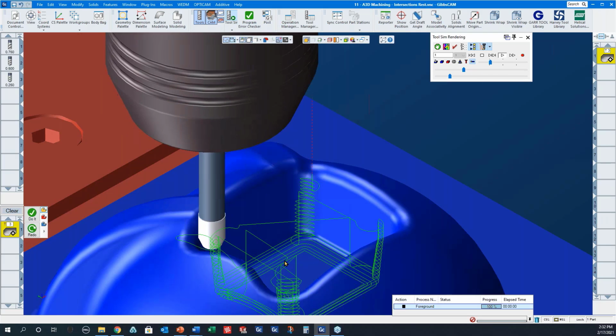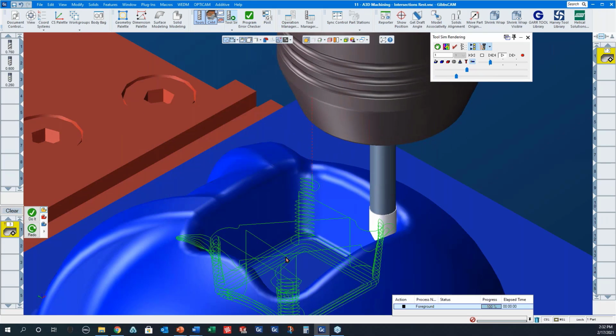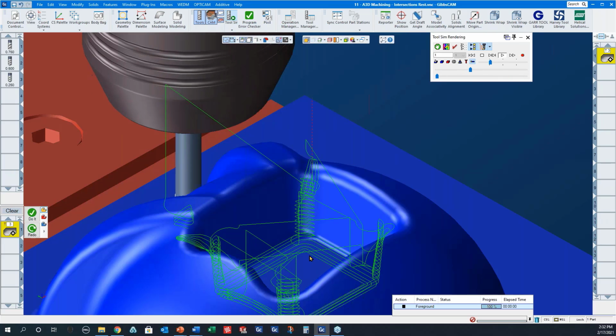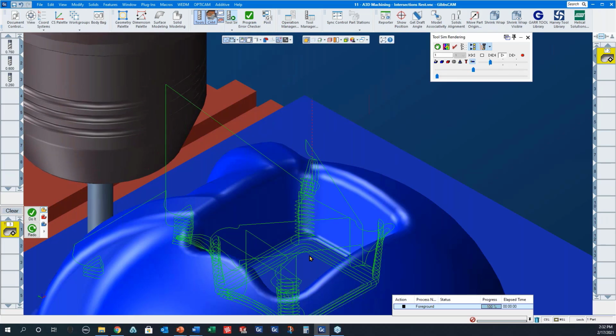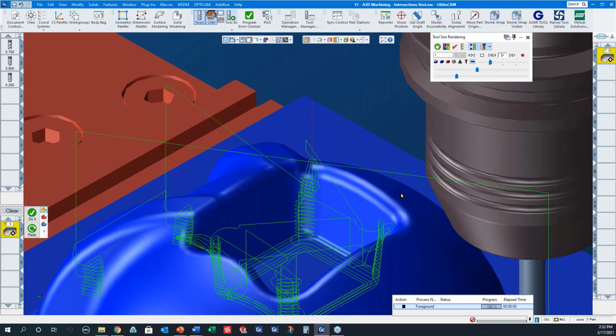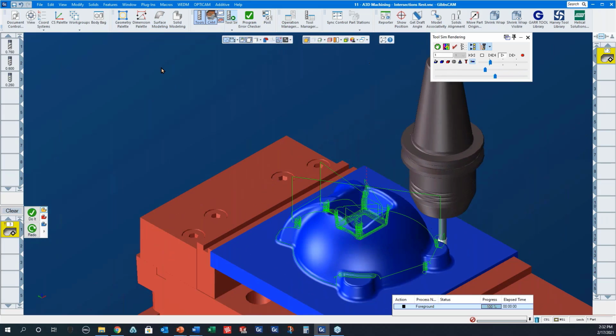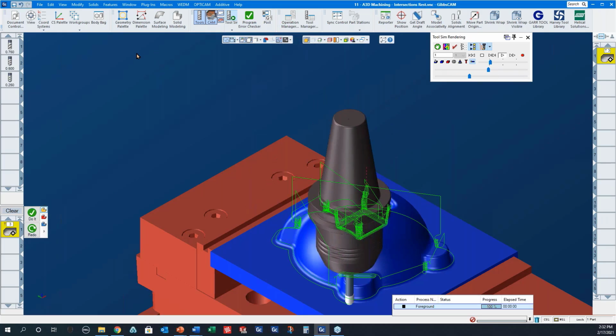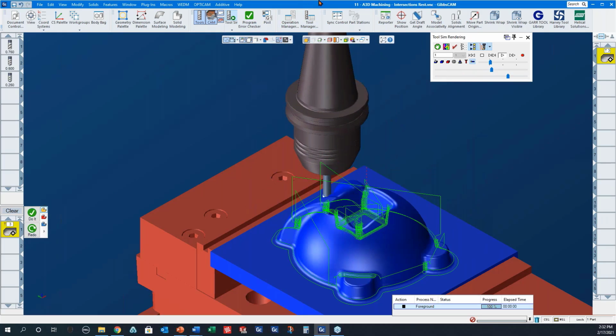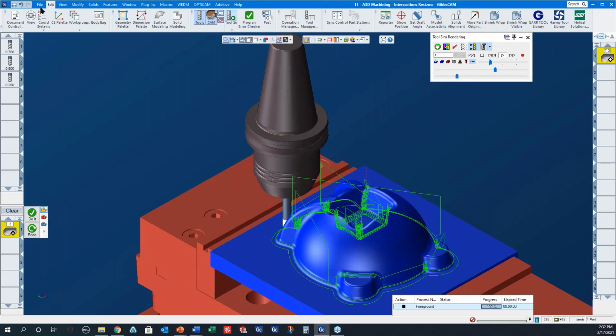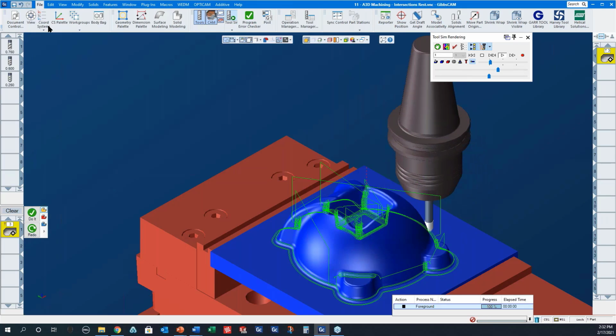Quite often, that's when you'll break tools, especially with tiny end mills like 10 thousandths diameter end mills like we use. You don't want to be running the tool up and down in Z. That helical motion is much better. Okay, so that's intersections rest.